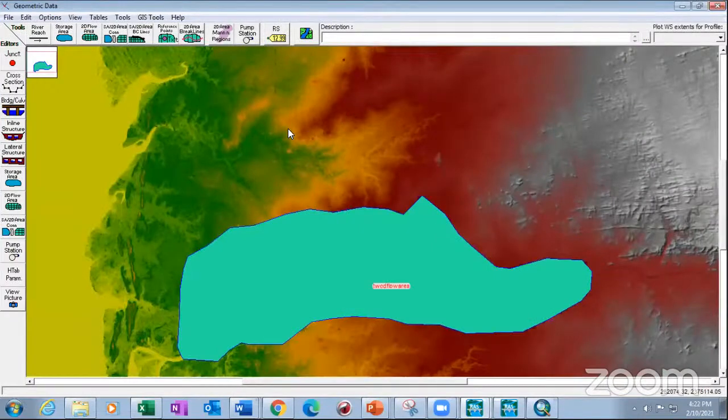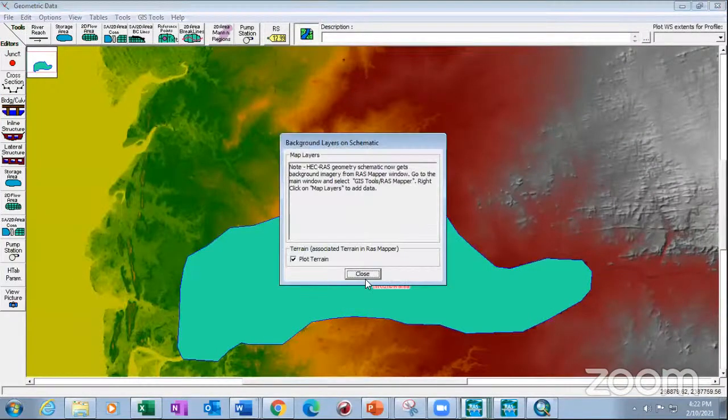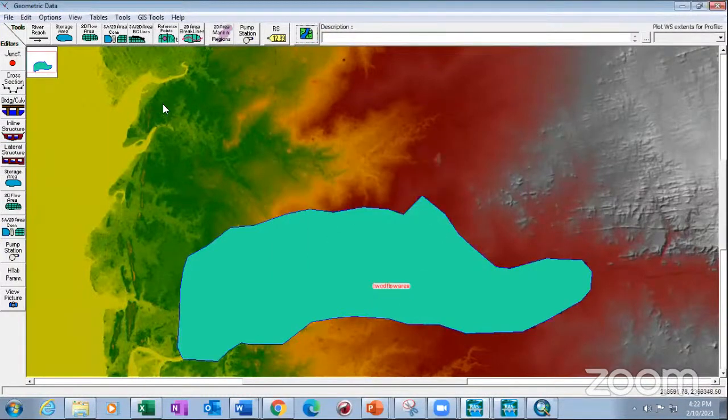If this window appears, sometimes it will look blank. So click on this and just say okay. It will appear and show you the entire screen. Now just click on 2D area and then trace along your river, having certain excess area, so that it will catch the flood inundation also. Okay, so this is a flow domain.